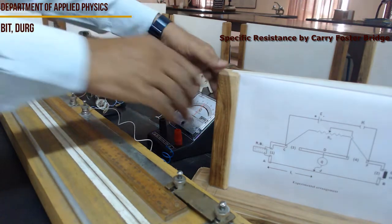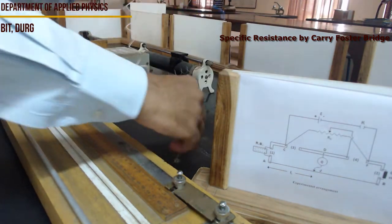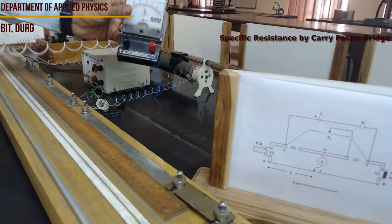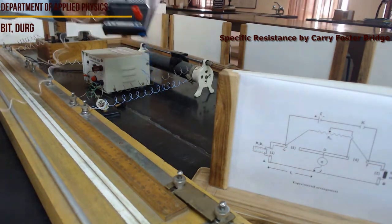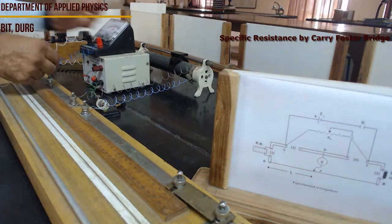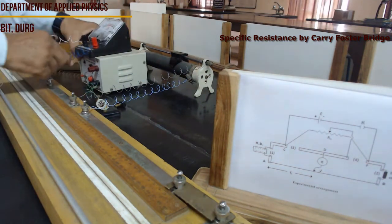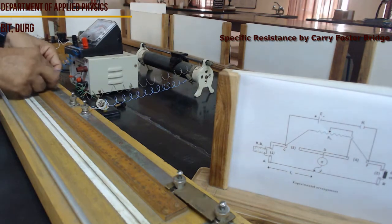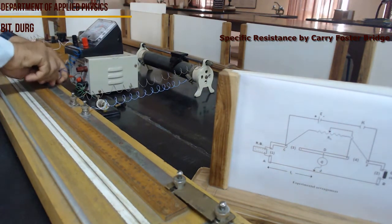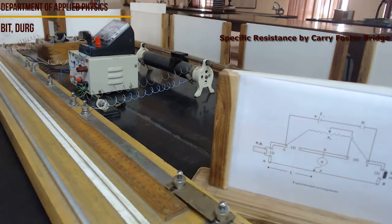Now the galvanometer, this is the galvanometer, and one end of the galvanometer is connected to the jockey. You can see one end of the terminal connected to the jockey. This end should be connected to the central terminal. So this end is getting connected to the central terminal of this Carey Foster bridge. Now the connection is over. I am having this jockey.